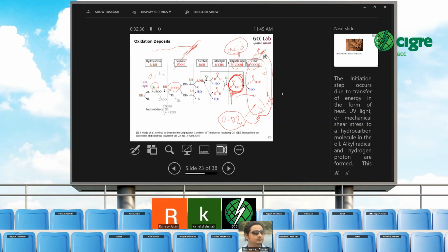Mostly, but if the gases in the tank are normal, nothing, and we found high hydrogen, for example, in the cable box, yes, now you have a problem in the cable box. But in this kind of scenario, normally we have separate cable boxes where the main tank DGA dissolved gases are fine, no hydrogen. But in cable boxes, if the hydrogen value is very high, there is a counter argument that it is because of stray gassing.